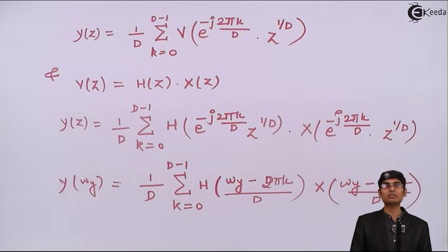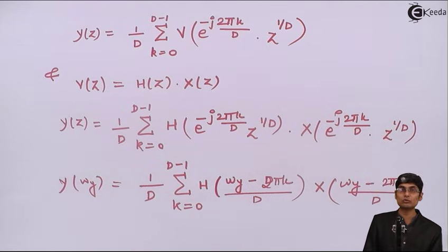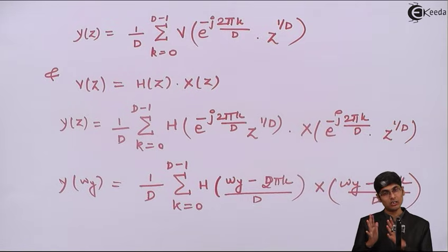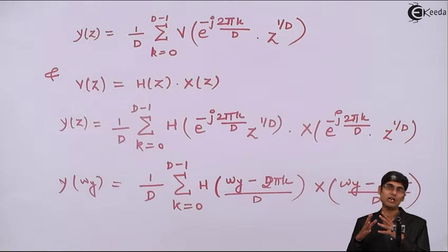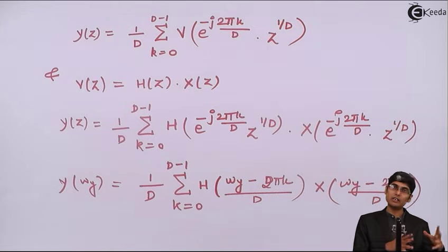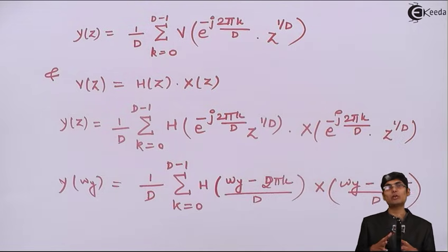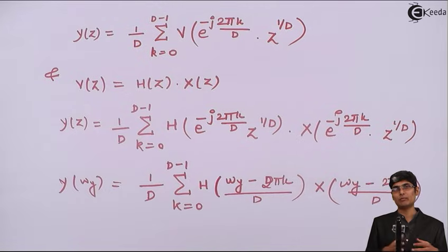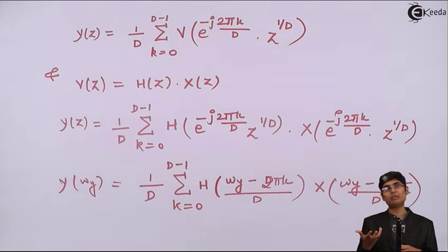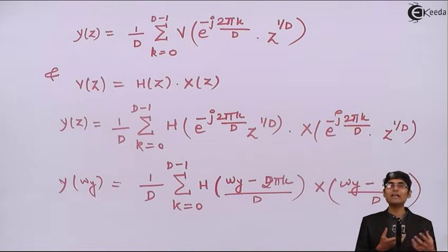So whenever they ask you for the process of decimation as a proof, you have to prove it by showing decimation as a process with a filter at the start and then a downsampler, because we need to restrict the spectrum of the input signal to avoid aliasing, and then we have a downsampling process. So the output sample will be the convolution of the impulse response of the filter and the input samples. This whole thing is given to the downsampler, and then I pick up only the integer values of m. That gives me the downsampled version, that is y of m.